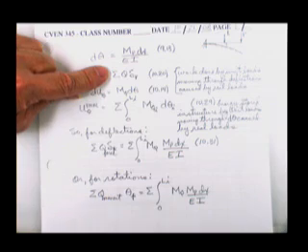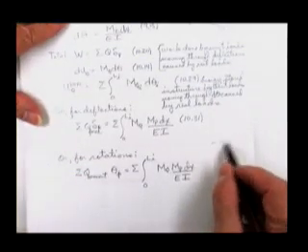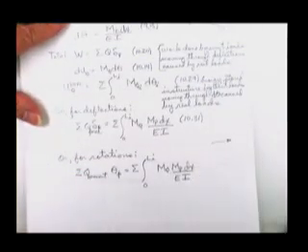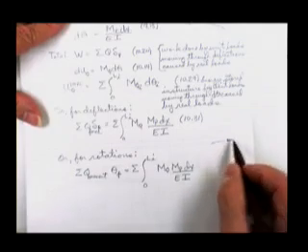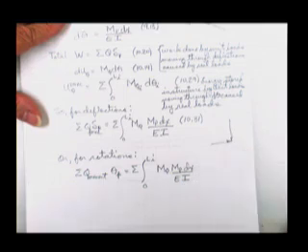And the direction that you put the load is the direction you will get the answer. So if you want a horizontal deflection, you'll be putting a horizontal unit load on the structure at that point. If you want the vertical displacement, you'll be putting a vertical load at that point.